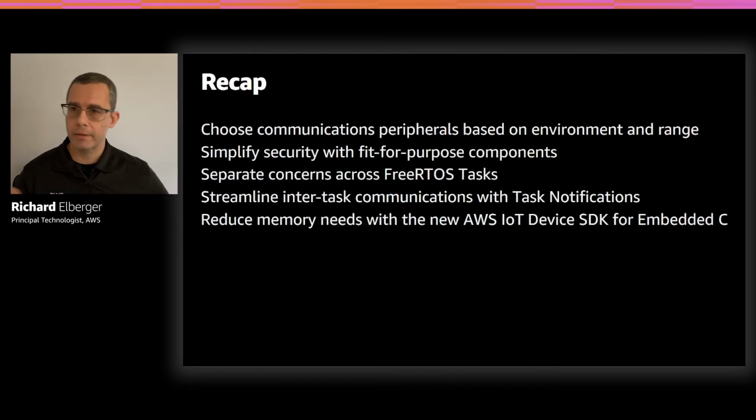So let's do a quick recap then. First, remember, don't feel married to a communications module. Do your due diligence for every use case that you have to implement. It's really easy to fall into some design traps when you're under time pressure. Take the time to properly design and encapsulate your FreeRTOS tasks so you have a much easier time managing your code base. Finally, many optimizations have been made to the application protocol libraries that are now part of your FreeRTOS project, including memory utilization enhancements.